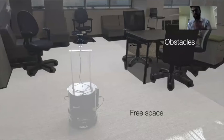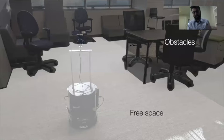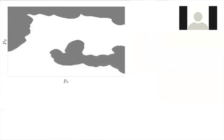Then the next step is to define the set of states that we want to avoid. So in this case, we don't want to bump into furniture, so obstacles are given by the furniture and everything else is free space. Let us see the same environment in a top view. So gray here is the obstacle and the white is the free space. One thing to note before I move ahead is that this is just an example. In the actual scenario that we're interested in, this gray region would be all the unexplored part of the environment, so everything that we haven't sensed yet, and white is everything else.